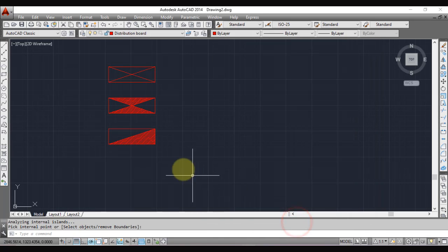OK. Hence you can see we have drawn main distribution board, sub-main distribution board and distribution board, and all these three equipments are under the same layer. Okay, so these three equipments are drawn under one layer. So after all, here we have one more very important concept of block. We have discussed in the AutoCAD part that every object in a drawing should be in a block. This is the way of professionals. So I have to convert these three objects into blocks.